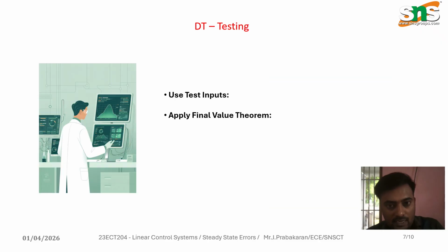After designing, we need to test the system. We use different test inputs like step input, ramp input, parabolic input. Also we use the final value theorem to calculate the steady state error mathematically. This helps us predict system performance before implementation.